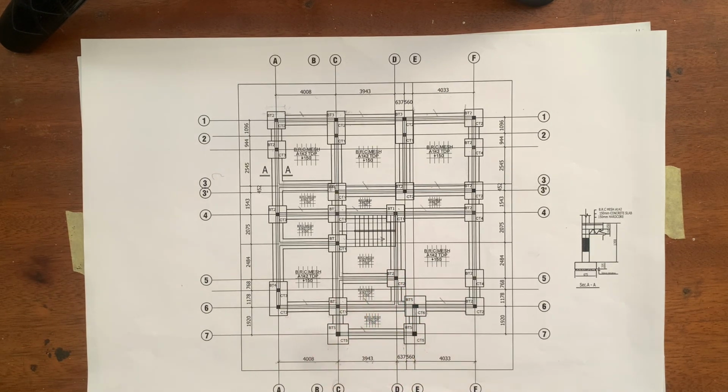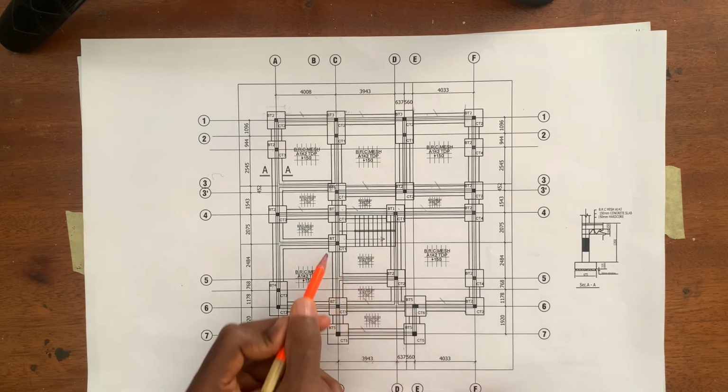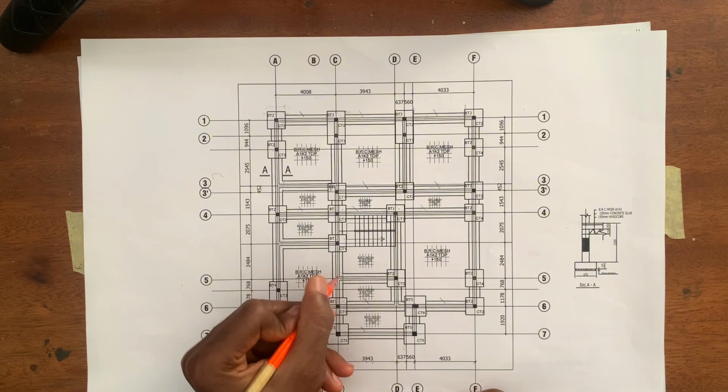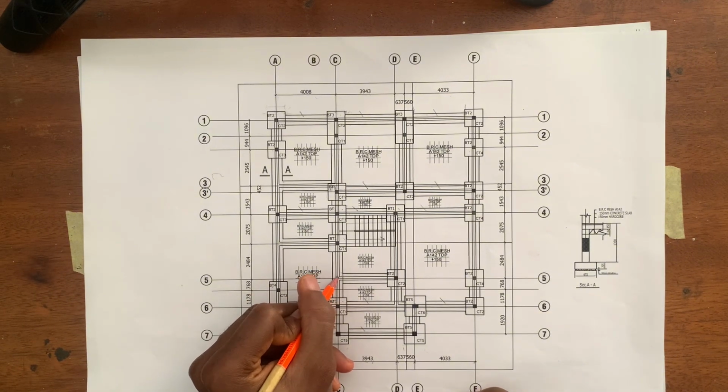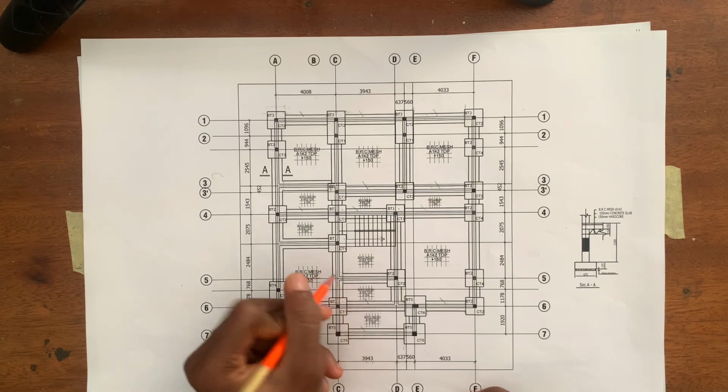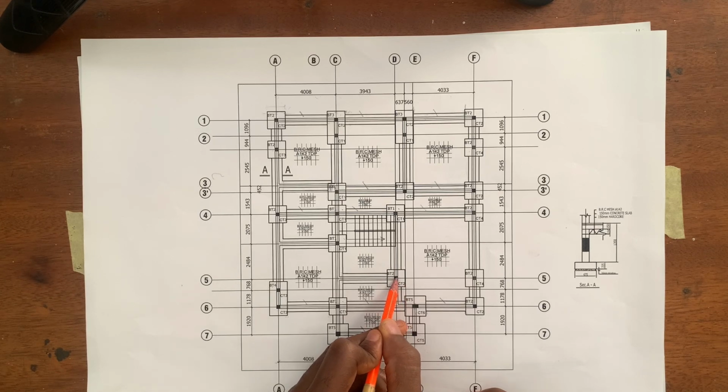So now, in order to get the distance for this trench, since we know the center to center dimension from here to this end, that's from this point to this point, so this is the center line you are seeing here. So all we can do now is to minus this distance from this center line to the tip or to the edge of this trench, and then minus the distance from this center line to the edge of base type 2. So you know that the length of base type 2 is 1,200. So half of it will be 600.